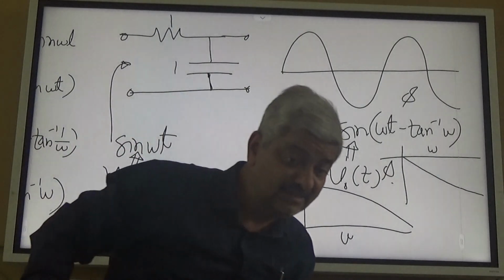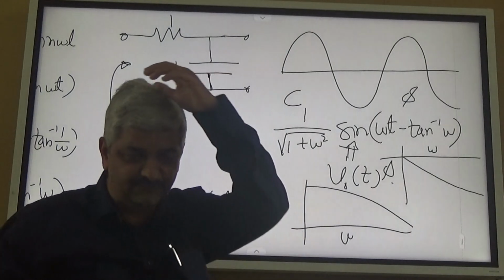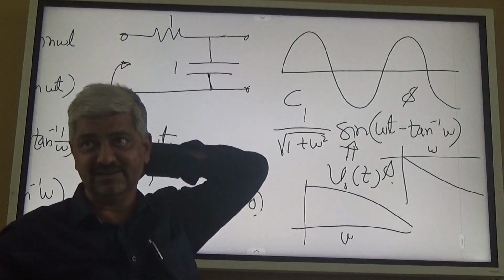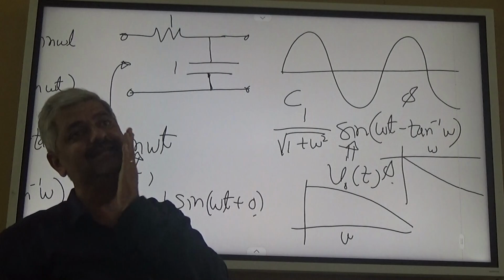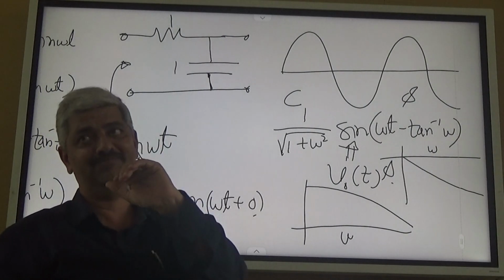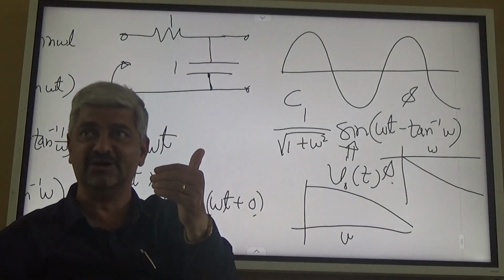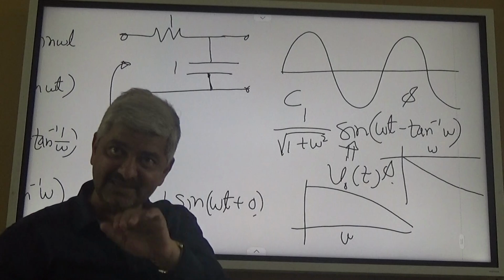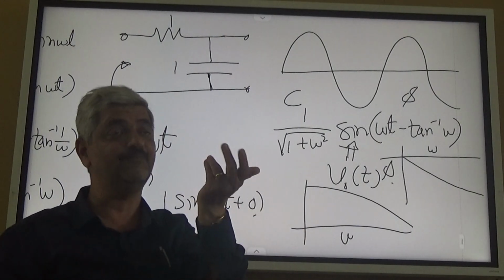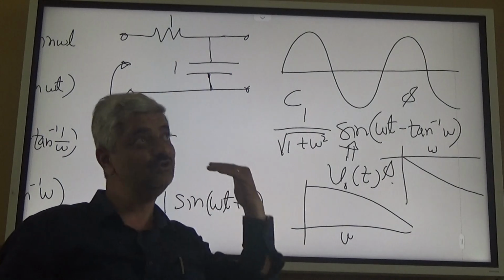And obviously here I have taken amplitude as 1. Now if input amplitude is different, that will also reflect. So rather than saying output amplitude, I go for the ratio, amplitude of output upon amplitude of input, that is called gain. So that gain is a function of frequency, and here I have started with phase of 0, I can start with a different phase.